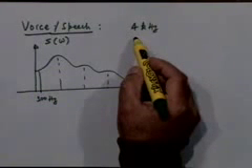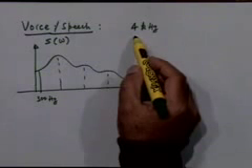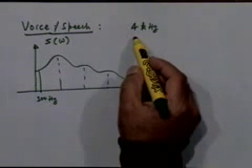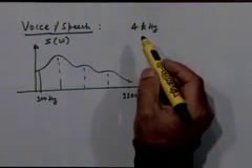But the actual amount of information that I am conveying to you is something different altogether, right? In fact, in terms of bits per second as the measure of information, it is really a very small amount. It's something like 100 to 200 bits per second, right? Which, as you can see, is very, very small as compared to 4 kilohertz. This is 4000 and that is 100 to 200.